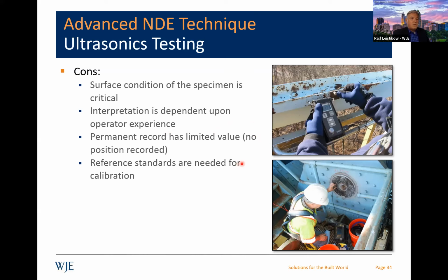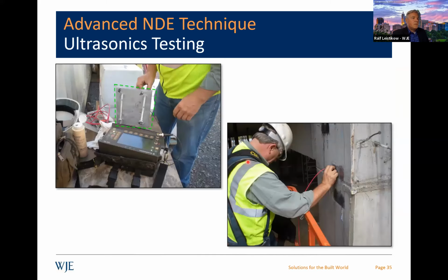And then you have to use a reference standard. So anytime you're doing this testing, you're going back and forth sometimes to recalibrate your equipment. There are standard thickness plates and such. You have to basically calibrate your probe or transducer. So that's kind of time consuming.